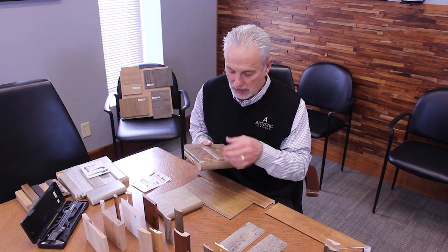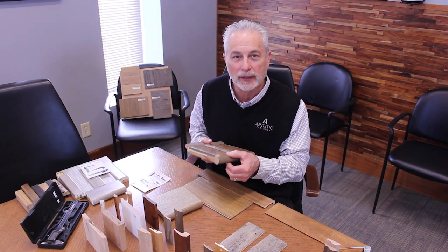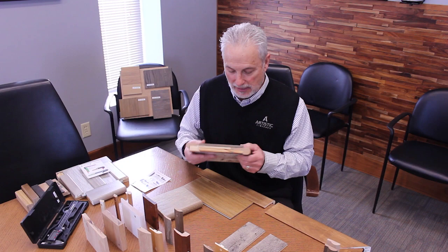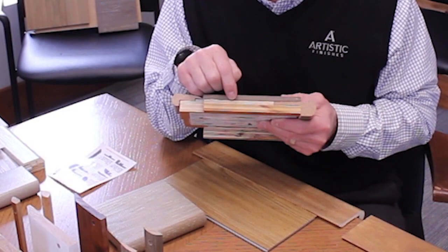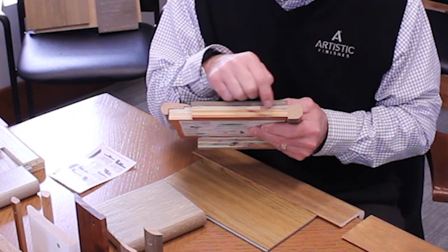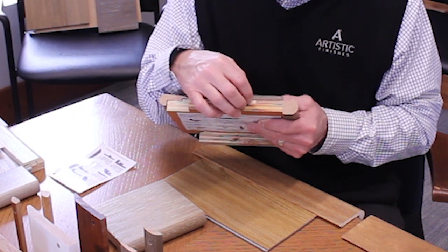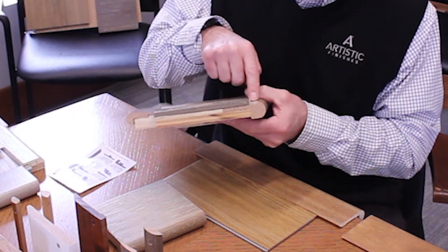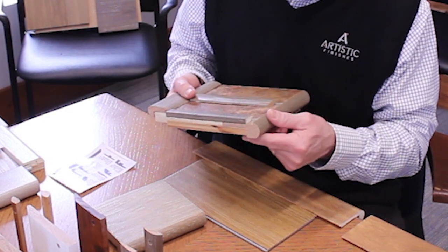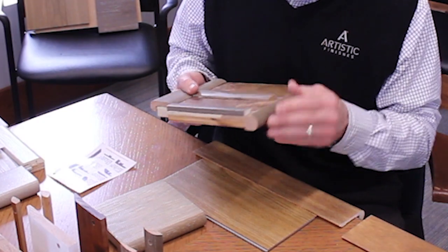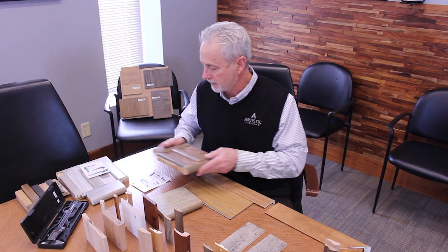So that if you're on a step, you see very little bit of the complementary wood. Yet it does follow the manufacturer's recommendations for a 1/4 inch underlayment. It lines up with the face of the profile, but allows the flooring to go over the top and be flush with the radius edge of the bullnose.